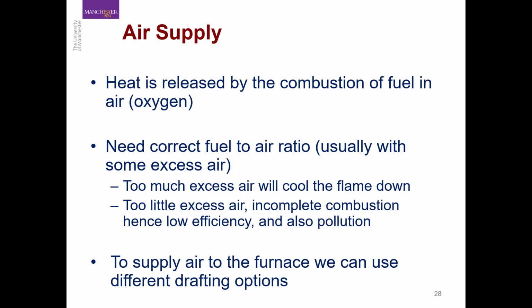ratio is being maintained. Most of the time we have to supply excess air to complete the combustion in a furnace. So it is really important that we maintain a correct fuel to air ratio, because if we have too much excess air, it will cool down the flame, in the sense the furnace might not reach the temperature that is required for combustion. As such, it is going to produce less heat, which can decrease the efficiency and increase fuel consumption.